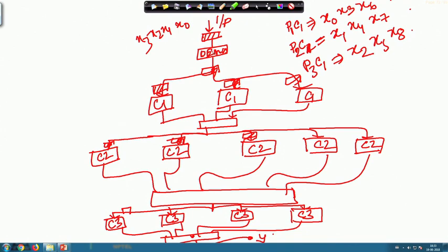That means from this particular demultiplexer block, all these x0, x3, x6 will be coming to this particular processing block. At this particular point x1, x4, x7 will be connected, and for this P3 C1 the samples x2, x5, x8 will come to this particular processing block. Then again that will be these 3 inputs.